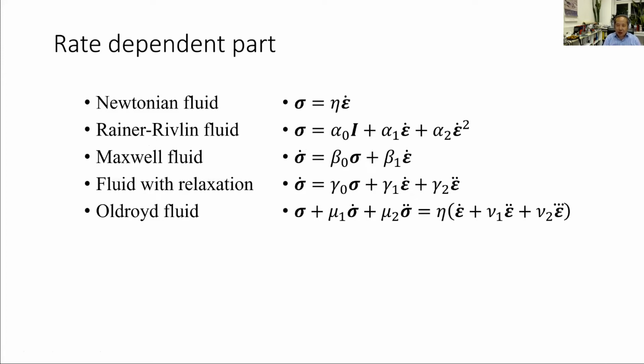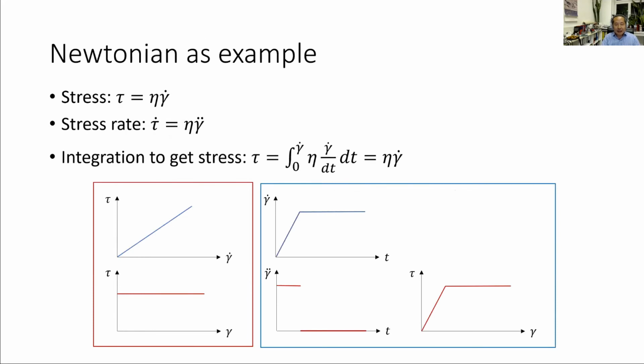I want to take this one and turn it into the stress rate. And you can see here, we could take the time derivative, right? On the left-hand side, we got the stress rate, which we need in our incremental formulation. On the right-hand side, this is already stress rate. If you take the time derivative, what do you have? You have the acceleration, we call it here, a kind of acceleration strain, right? The higher order. And there is something interesting, I will show you here.